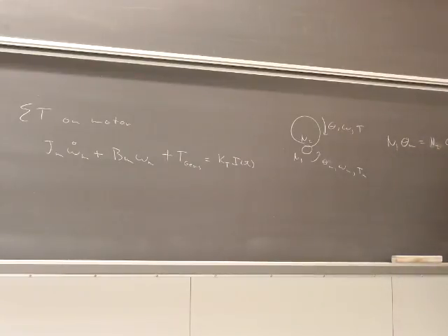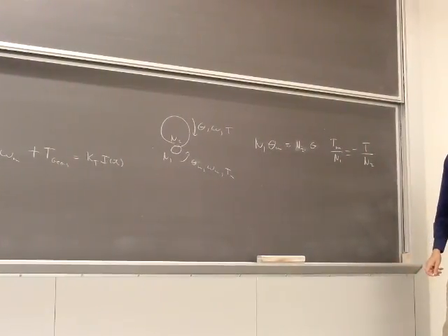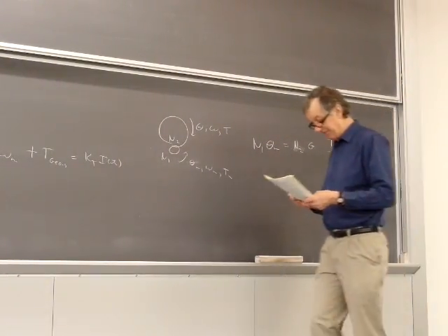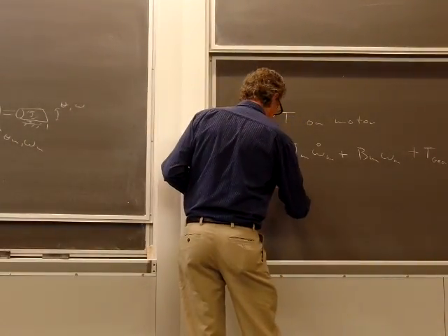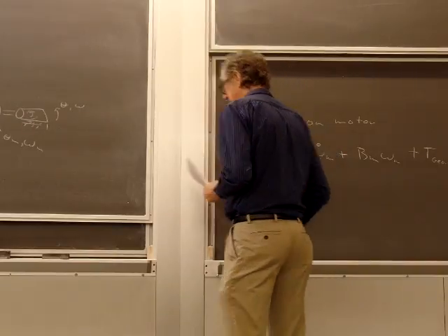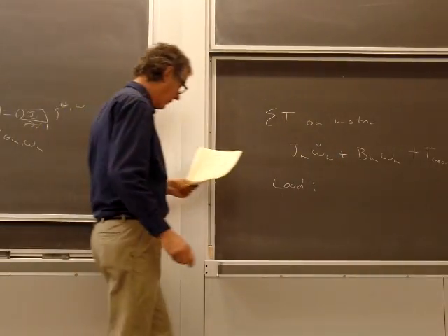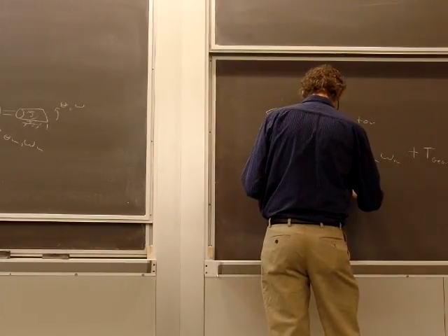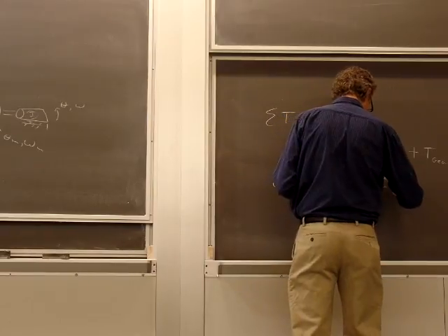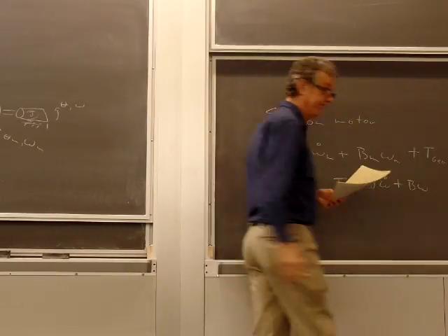And then same thing for the torques. Because of the way I drew the arrows, there's a minus sign in there. All right. Let's look at the load, the last part. The load has J and some friction to it. And it's whatever torque from the gears is acting on it: J omega dot plus D omega.